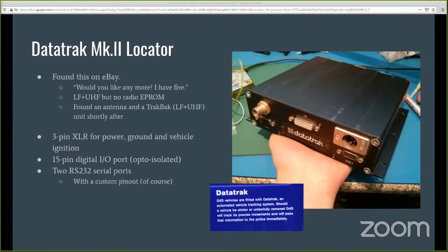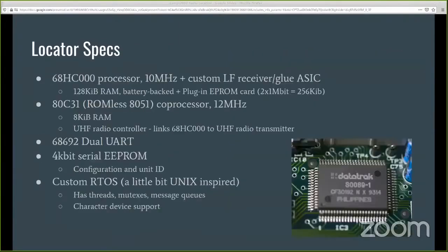There's also two RS-232 serial ports on here. COM1 is, I would call it a debug serial port from the sheer amount of noise it sends out about its navigation process. And this turns out to be very useful later on for reverse engineering it. COM2 takes commands, such as request position, and responds to them. It doesn't send quite so much debug information out, but it is all very, very helpful.